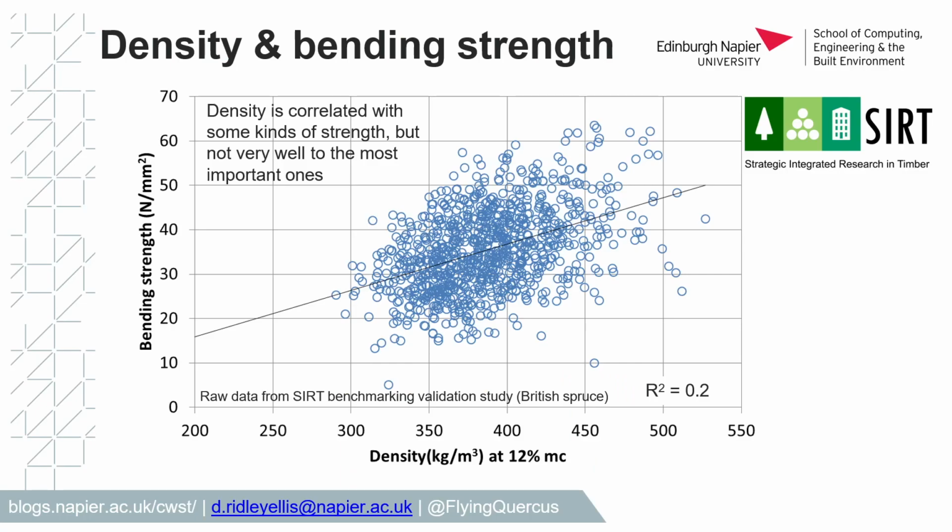So, before we talked about grading, and if we want to buy wood, grade it and sell it to somebody else without having to break it or damage it. There are things that help us do that: the density and bending stiffness. Density by itself is not the way to grade wood. It would not work.